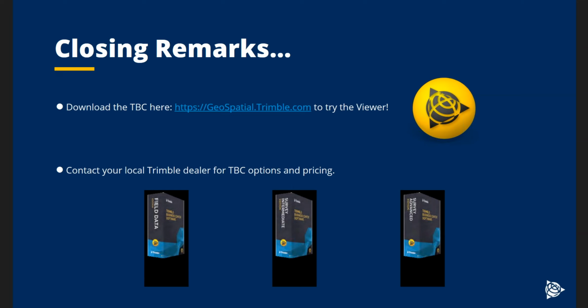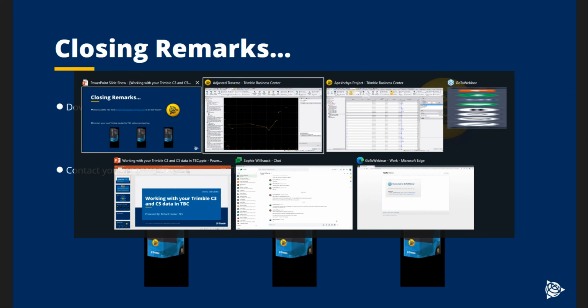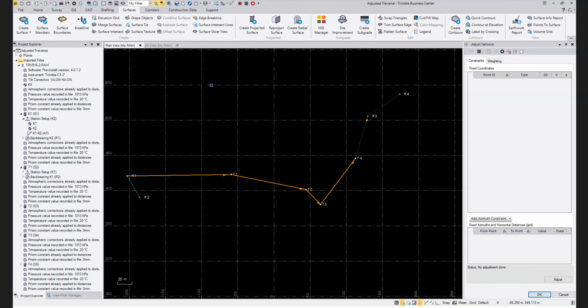Good question. The computation engine actually is very rich in Trimble Business Center and will take all possible options. And I can perhaps show you quickly now that I have it turned on. It can take all possible options for a coordinate and try to figure out what is the best coordinate for the point. And in the case of multiple mechanical total station observations, they're all weighted or seen by the computation engine as having the same quality. So it depends on the source of your computations.